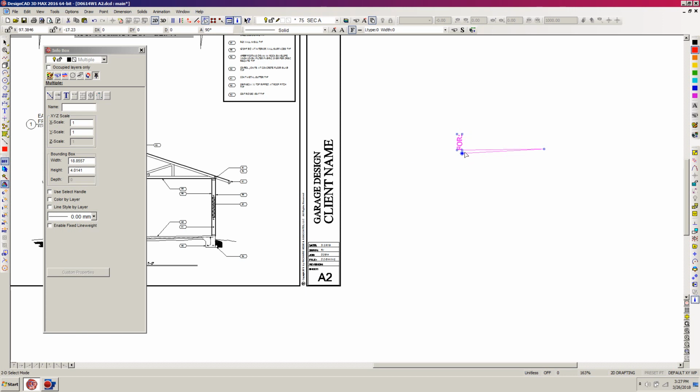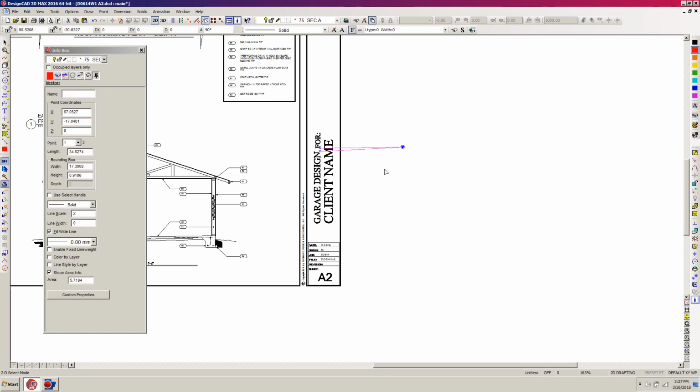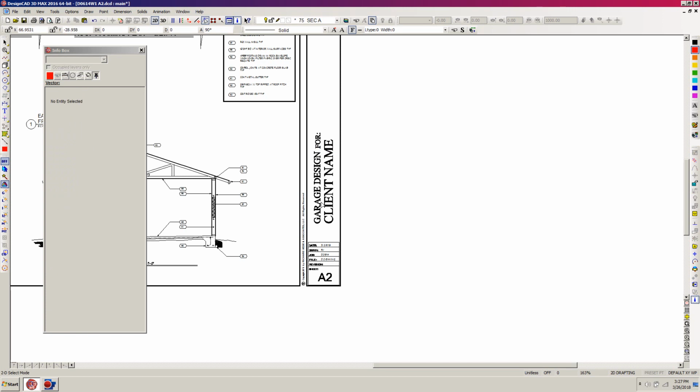because I'm going to reposition the word 4. Now I'm going to hit M for move again while they're still selected, and I'm going to right click at the bottom and end of design. Right click, snaps it in place, hit escape, select my spacer V, and hit delete to get rid of it. Okay, so now we have the first portion of our title.